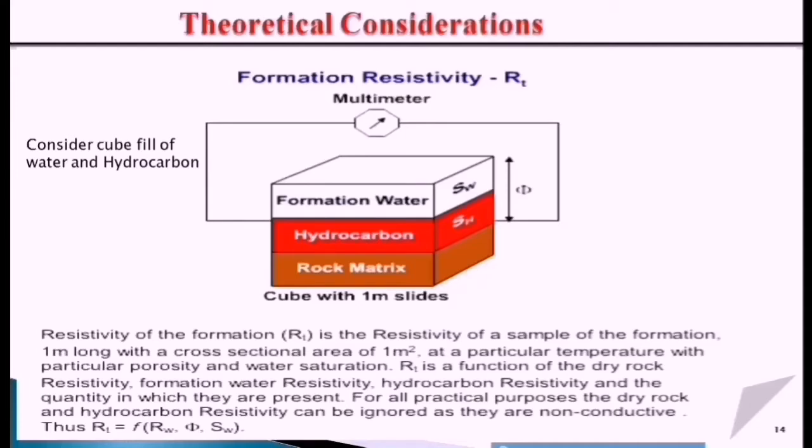But for practical purposes, the dry rock and hydrocarbon resistivity can be ignored, because they are non-conductive. So by that, the true formation resistivity is a function of RW, the formation water resistivity, and a function of the porosity and the water saturation.